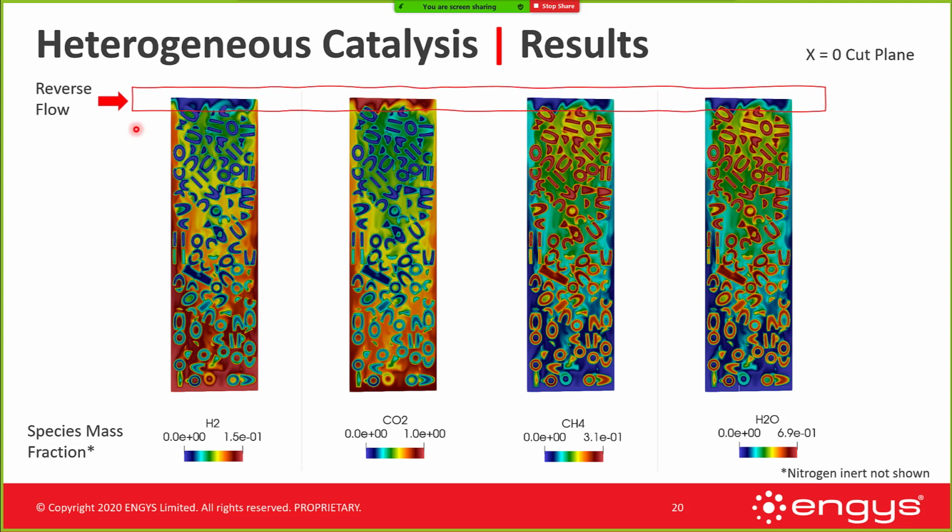One thing you might notice is that there's reverse flow at the outlet. So that's why you would see this sudden change and return to the entrance values, or everything was zeroed. So this could be gotten rid of by extending this packed bed up to an empty tube by maybe 0.5 meters. For this case, I really didn't want to do that because the mesh was already large enough and I wanted to take a look at the results. So I was very anxious to take a look.